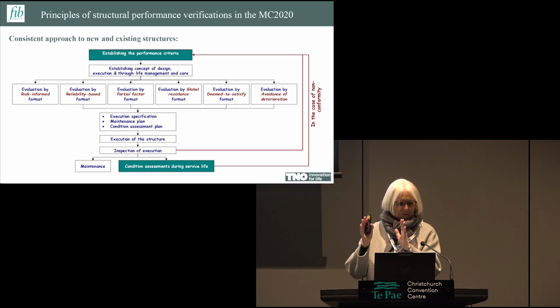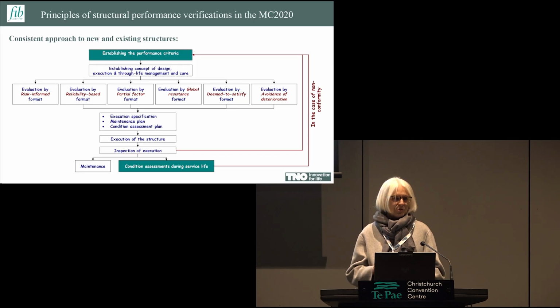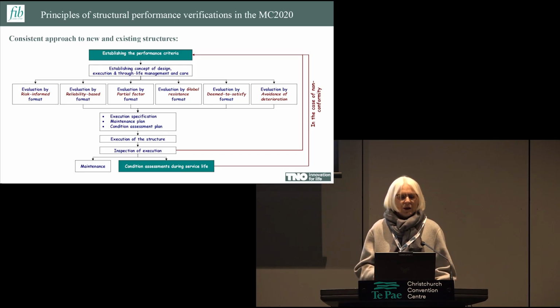Usually we will use the mid part of it, but know that there are also situations in which we can rely on reliability-based assessment, in particular for exceptional structures, in particular for assessment of critical structures, and we also have information on that, down to deemed-to-satisfy rules that of course need to be properly calibrated and connected to make sure that when we follow deemed-to-satisfy, we actually meet the same safety level that we aim to.